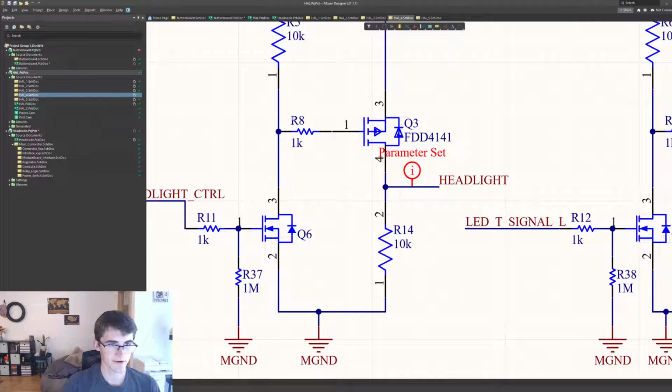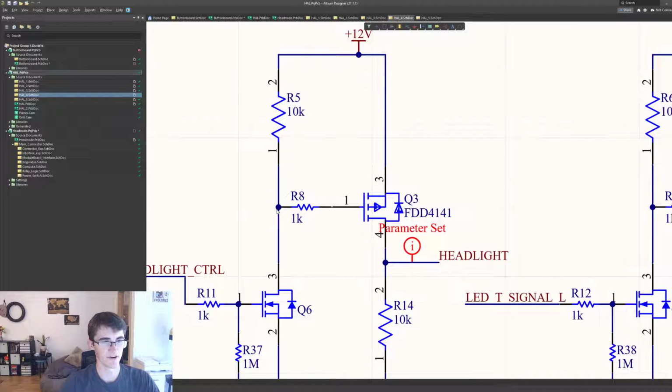So now this node right here by R8 is grounded after this control line turns 5 volts from ground. And now that that's 5 volts, this will now become 5 volts, and then there will be a difference between pins 1 and 3 for VGS here. Let's just say that isn't connected again. Then the 12 volt line would go through this 10K resistor, and the difference between the gate and the source would just be 0, because you'd be getting 12 volts up here, and then you'd be getting 12 volts through 1.